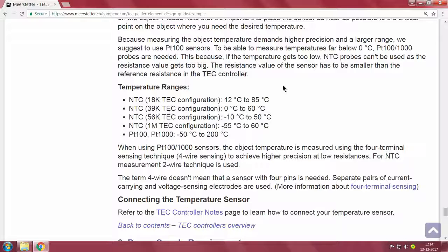So, here one more thing is often we have small chips which are taken directly from any of the standard websites, which you can continue to use, but by definition invariably we are expected to use 4 wire sensing, because we are dealing with thermal parameters, and all wires also have a temperature coefficient, and we are talking about small changes, 0.1, 0.2 millivolts change.